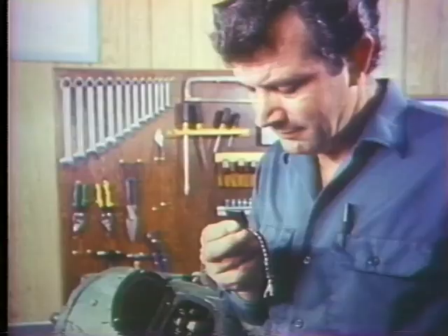We're going to look at evidence of two typical problems: threading and grooving. This commutator's threaded. See these fine lines cutting into the surface here? They look as if they're machined in. Copper is being transferred from the commutator to the brush. You'd find copper flakes embedded on the seating surface of the brush when you inspected it. Threading causes the brushes to wear rapidly. It's often caused by low brush pressure, contamination, or the wrong type of brush.